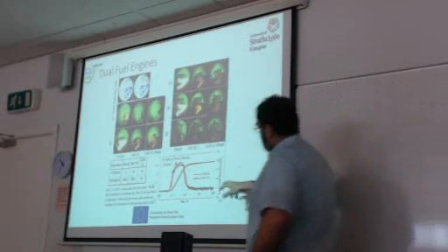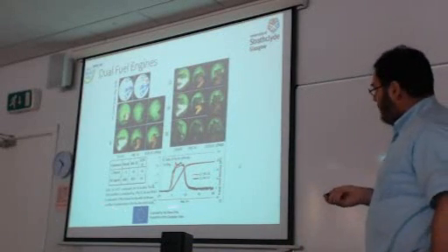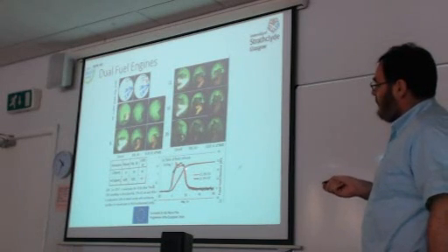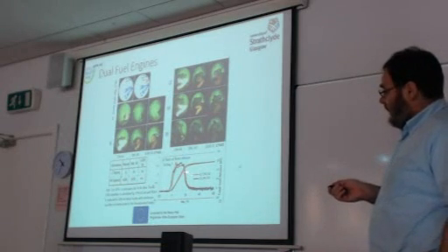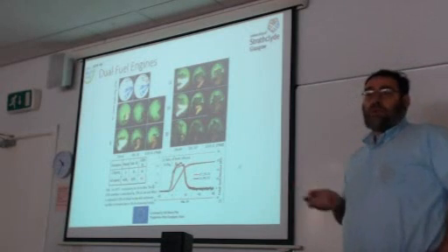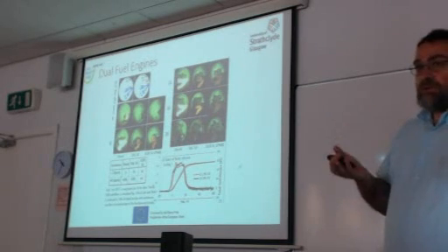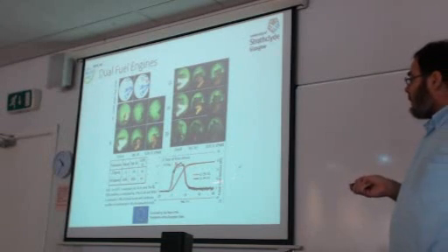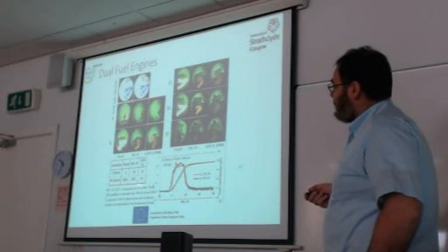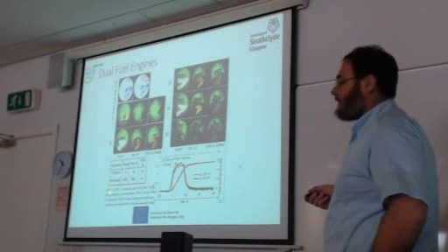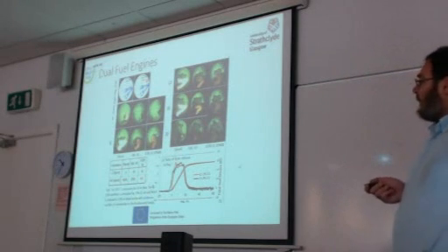And this reduces NOx by which way? So this reduces NOx because the combustion is lower. So you can see that what happens is the heat release rate. The red line and the black line is the heat release rate, cumulative heat release from gas ignition concept, and then by using EGR, you can see that combustion delays. So the heat is released more slowly than the case of the normal engine operation. So that reduces the maximum pressure and reduces the maximum temperature, or changes the temperature. And of course, this affects NOx.